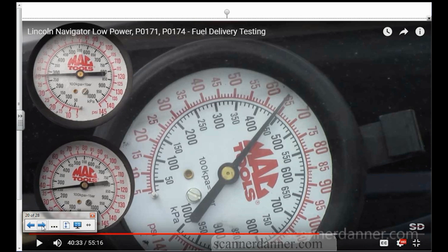So I replaced the pump, and the big picture here is my fuel pressure at idle. It's a huge difference, isn't it? It's a huge difference just at idle. You guys remember my fuel trims were positive at idle too when we started this? They were about 25 on the long term and 0 on the short term. Raised the RPM and it went 30 and 10. So it did get worse, but it was bad at idle too. And to the rookie, maybe that looks like a vacuum leak.